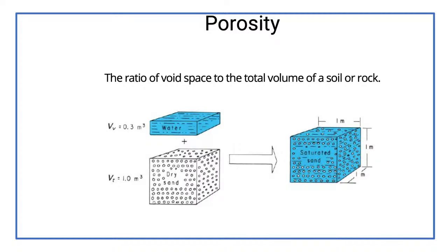An aquifer can change laterally, it can change horizontally, vertically. And so these conditions can change, so it becomes very challenging to just arm wave and say our aquifer has 30% porosity, because you need to measure that, and we do that through pumping tests and other measurements, and we'll talk a little bit about that later. But this is the basic concept of porosity.